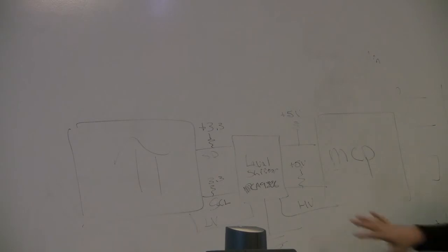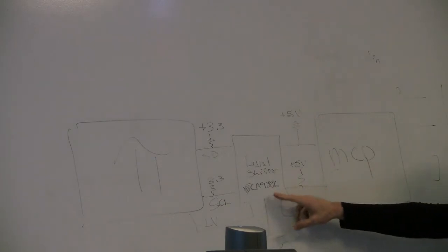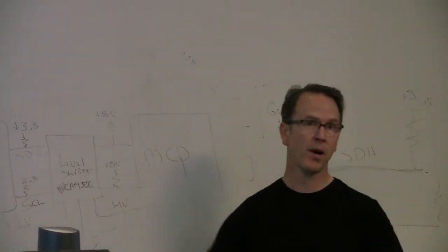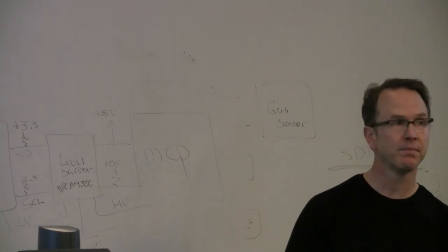This would be a good way to do it, and the nice thing about this too is, with I2C, what, 64 devices? Something like that, right? As long as you don't have 2 things with the same address. If you think of it as an expander, you can have all sorts of stuff hanging out over here, all with its own 5-volt power supplies and all that kind of stuff, and you're not taxing your power drain on your Pi. So you could do that.